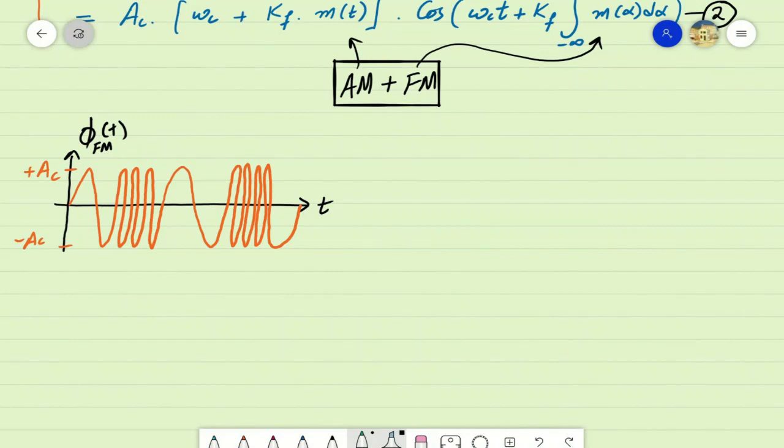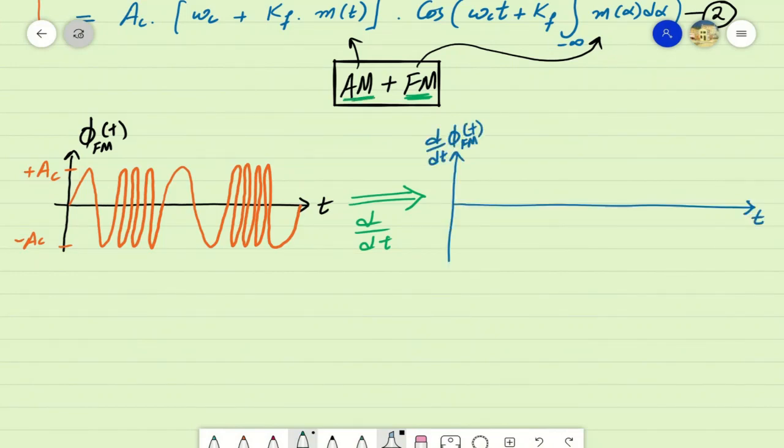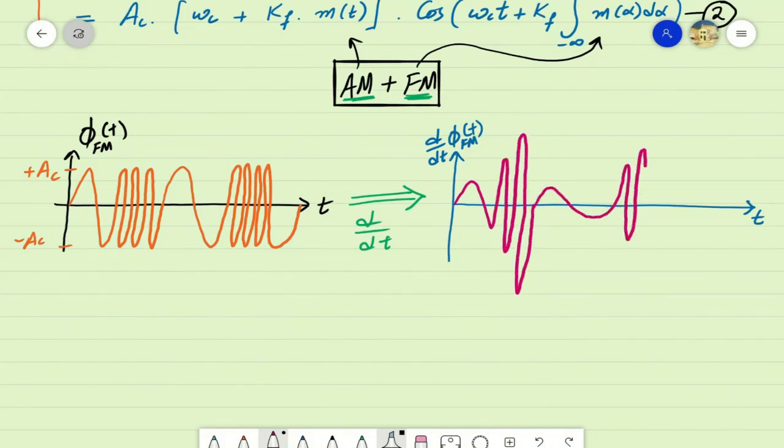After this signal was passed through a derivator, we have observed from equation number 2 that the derivator translates all the frequency variations in the received signal into amplitude variations as output of the derivator. So at the output of this derivator, we have a signal which represents the information signal over its instantaneous frequency as well as peak amplitude, that is jointly modulated in terms of frequencies and amplitudes.